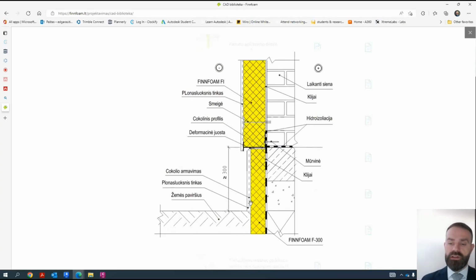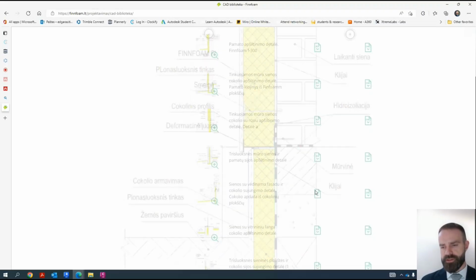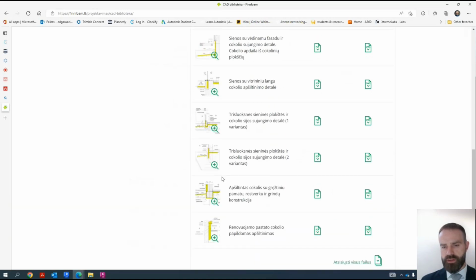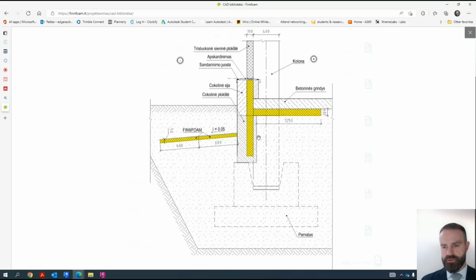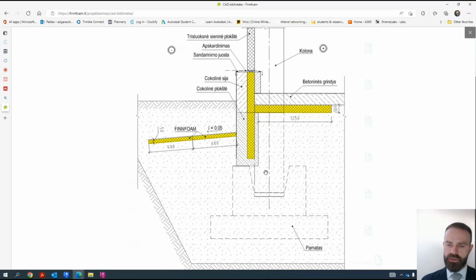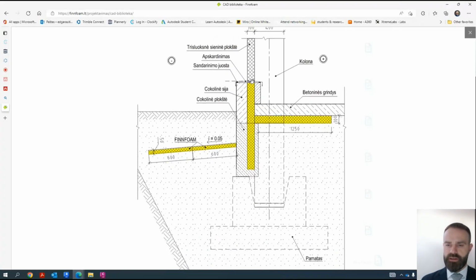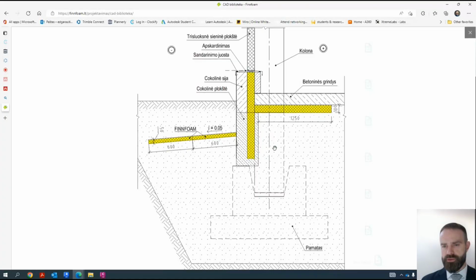And in here you have all the layers, so it means you need to take all the data from the manufacturers who are presenting materials. So for foundation, insulation for foundation, plastering, bearing walls and other parts. If you create all the things by yourself, you can make mistakes, because it's important to follow real details, real construction elements, and how they should be implemented in your project.